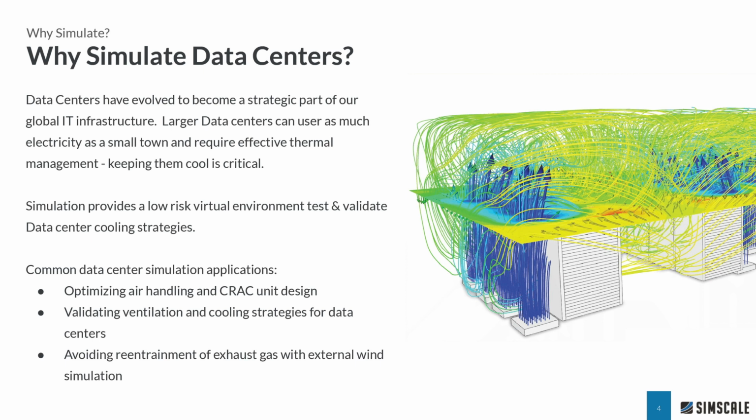Now, more specifically, what you'll often see in a data center are problems like recirculation at racks. You've got hot air blowing out the back of a server, recirculating on itself, going back into the inlet. Data centers are considered mission critical, and what that means is that 365 days a year, 24/7, they need to be up and running. Most data centers I've worked with usually have 3 instances to allow for redundancy. It is just never acceptable to have downtime, and that is avoided at all costs. So this means they need to stay cool as well.